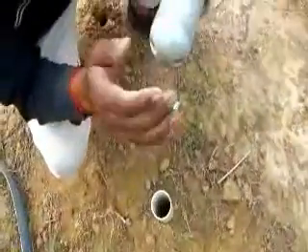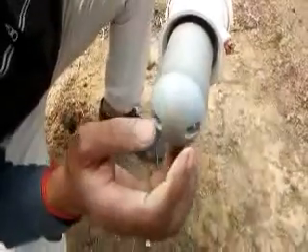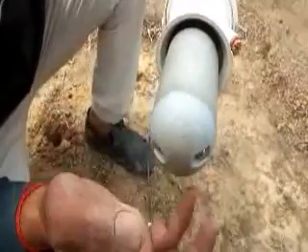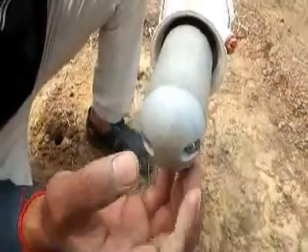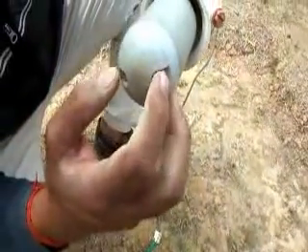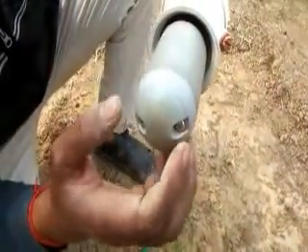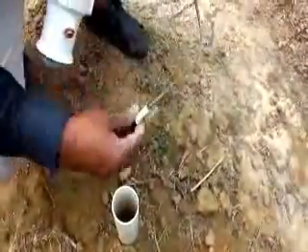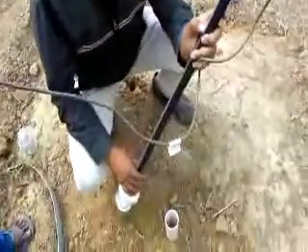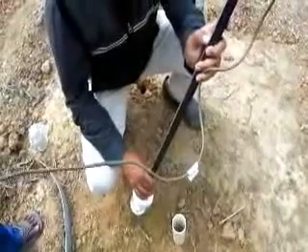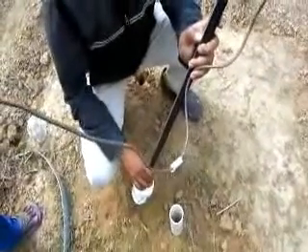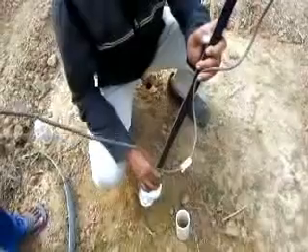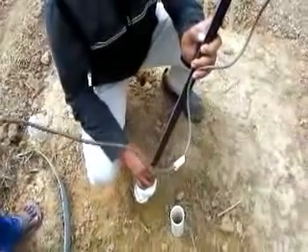So now you can see it has a bulb which uses frequency domain. Frequency is created to measure the soil moisture. These are 2 sensors which measure the frequency, and it goes inside, and it has a readout unit here which is connected to give you directly the soil moisture in terms of volumetric unit.